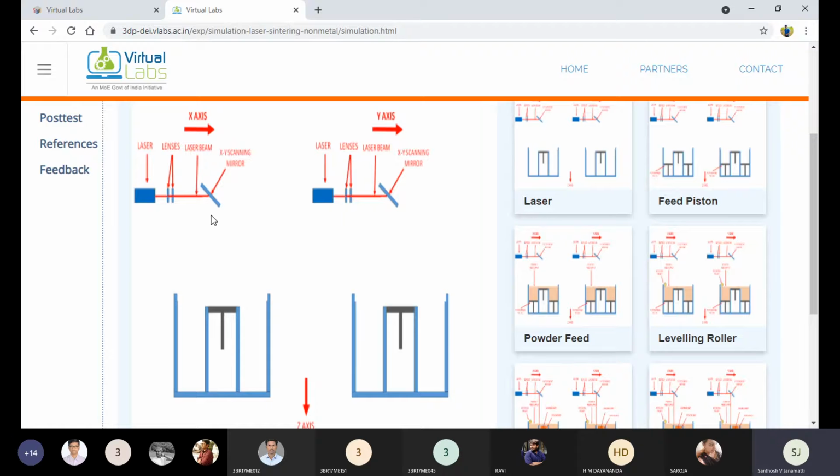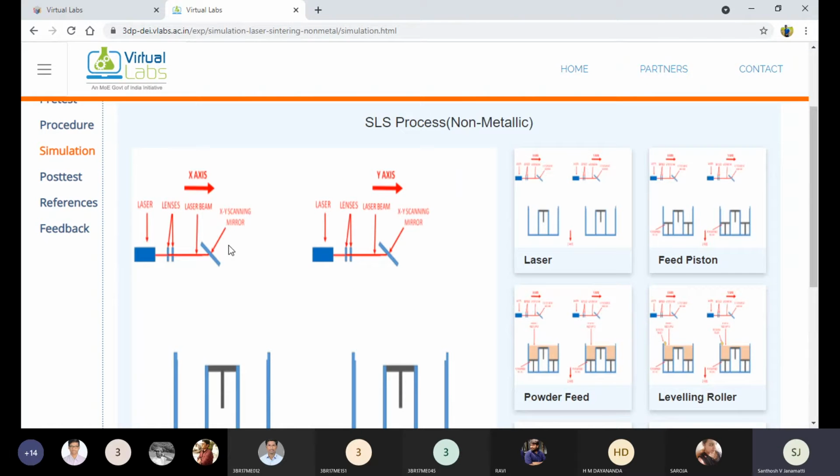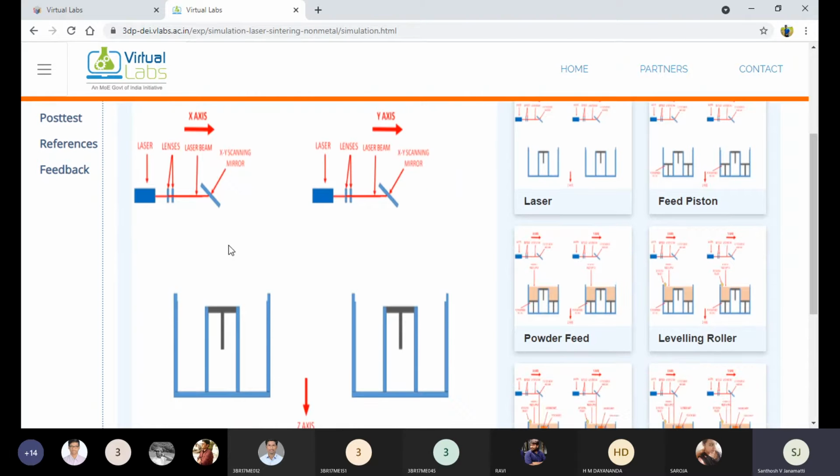That laser beam traces the raw material. As the raw material is fused, the atoms combine with each other, and in that way layer by layer they also combine. First the atoms combine, hence that becomes the first layer. Thereafter a fresh amount of material comes over the first layer. Again that powder is traced by the laser beam. Now the atoms join together due to the fused heat, and the second layer is combined to the first layer. That is the way we can build our 3D product.